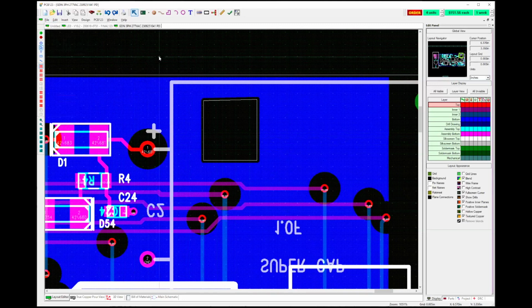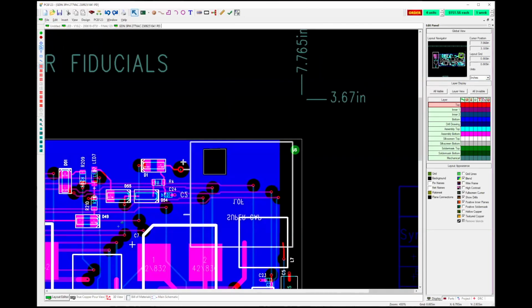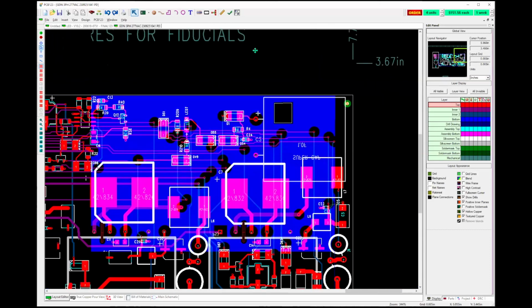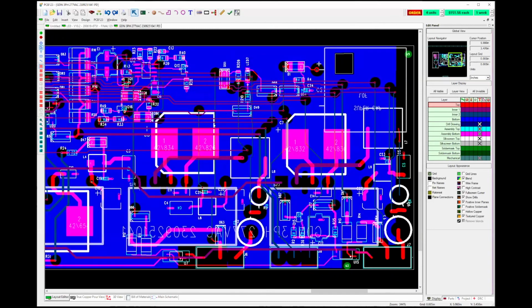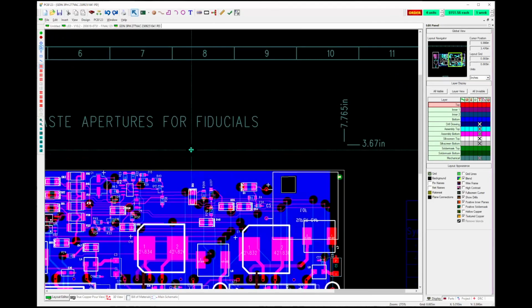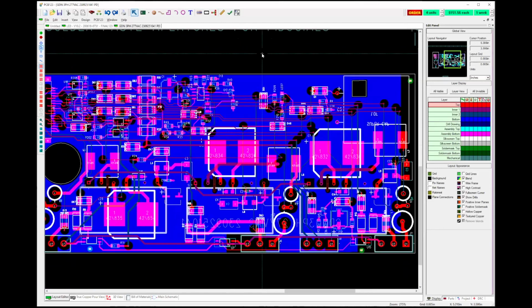Oh, it was more involved than that. I had to import the graphics into a Gerber editor and then save that Gerber and then import that into my board file to get the actual image I wanted. It was a pretty involved process. I got pretty good at it when I was working at Sunstone years ago, but if you don't have an actual Gerber editing tool, you probably won't be able to pull it off. Did that answer the question at all?